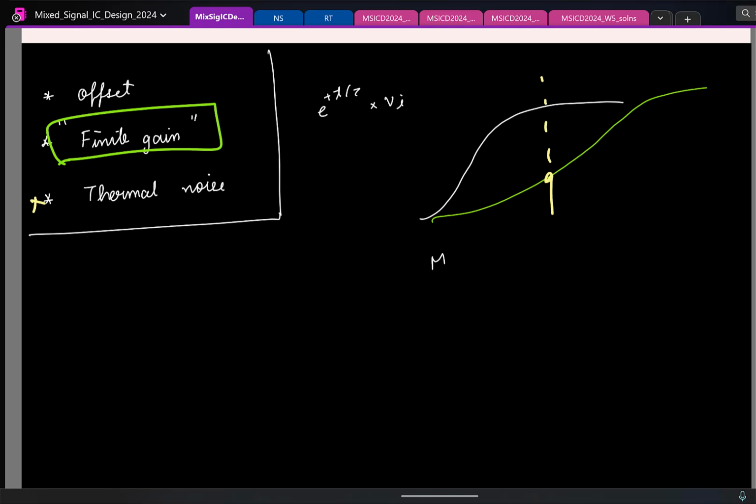If a signal is not in any of the defined logic levels, we call it metastable. And that is effectively what will happen if the, within quotes, gain of the comparator is not good, right? So now basically the logic will depend on random noise in the circuit and how the succeeding digital logic is kind of detecting this.